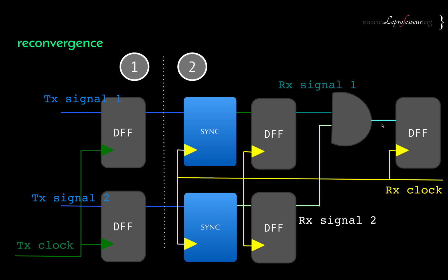And you would want to avoid all sorts of logic which toggles the input signal of the D flip-flop too much. Too much means that otherwise it becomes another clock. Okay, so the clock toggles, right? And at each edge you are sampling the signals.